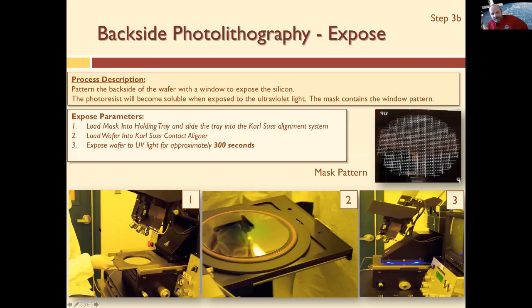So, backside coat looks about the same as that other wafer. I can tell it's coated because you've got the tweezer marks here. Our tweezers damage the photoresist. That's why we only use the tweezers on the edges. Now we've coated the front, we've coated the back. Front is first because that's going to be front side down, shiny side down, and we're going to pattern the back of the wafer. So that's the second coat.